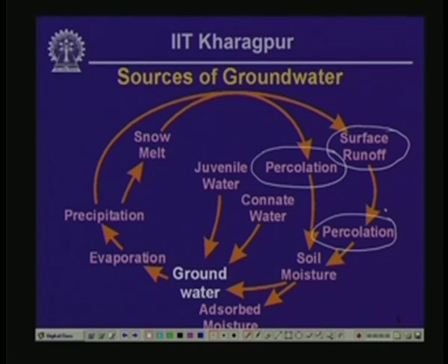A part of the soil moisture is going to be available in the form of groundwater, and another part is going to be locked within the matrix in the form of adsorbed moisture which is tightly held by chemical bonds on the surfaces of the soil particles, and another part is going to be unavailable for use because they are going to be trapped within non-interconnected soil voids, as we are going to see in the next little bit.